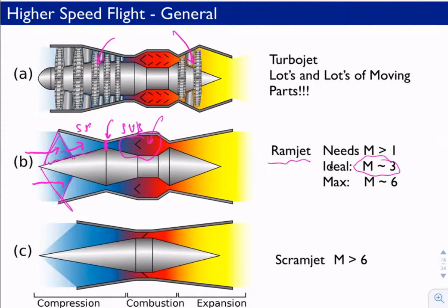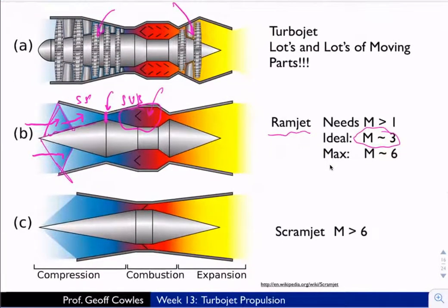As you get to higher and higher speeds, it becomes necessary to use supersonic combustion ramjet engines. So this stands for supersonic, the C is combustion, and then ramjet engine. So this would be for a hypersonic vehicle or a hypersonic missile. It would use this. You don't see the throat, so we're not slowing the flow down. We're not basically throttling the flow back to subsonic.